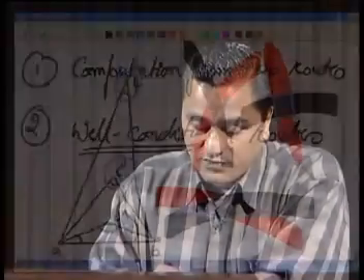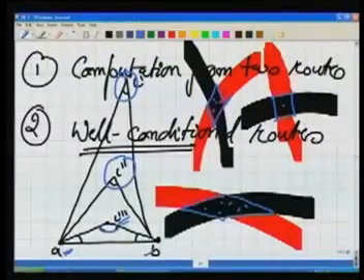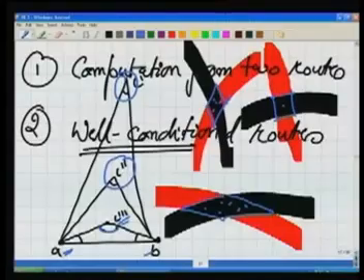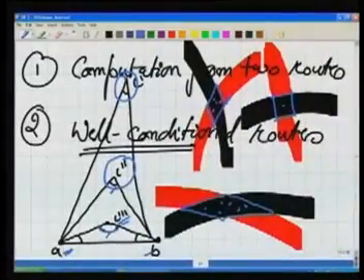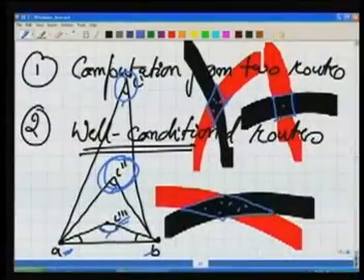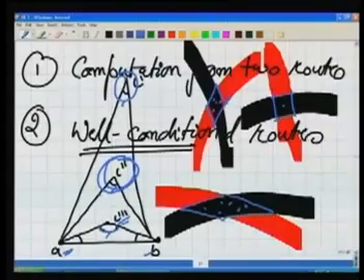So, uncertainty in locating point C double dash is least. So, what we are doing here is starting from 2 known points, we are trying to establish the third point, and in establishing the third point we have some uncertainty, and it depends upon what kind of angles we are choosing, where this point is. If the point C double dash is such that the angle of intersection here is 90 degree, the uncertainty in establishing C double dash is least.